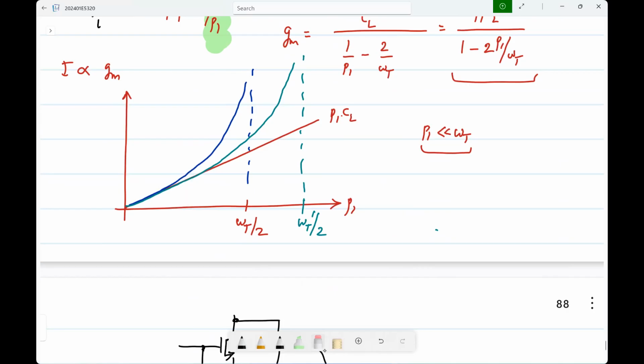You understand? So if you have a super linear dependence of power on the frequency, and you are able to use two circuits at half the frequency, it seems like the right thing to do. Whereas if you are operating where it is linear, there may not be an advantage in this respect. There may be other reasons, since there are many reasons why you make architectural choices. But if the power is exactly proportional to frequency, then splitting it into two parallel paths at half the speed doesn't really buy you anything in terms of power dissipation. Whereas if the power is going more than in proportion to frequency, then it makes sense to do this.